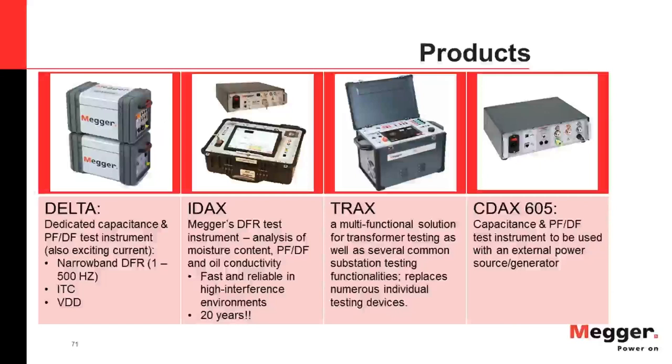There's a lot of different considerations you have to keep in mind before you apply any voltage to a service aged transformer, drained of oil, still of course oil saturated. You need to look at combustibles in the tank. You need to look at clearances between what you're energizing and any other parts.